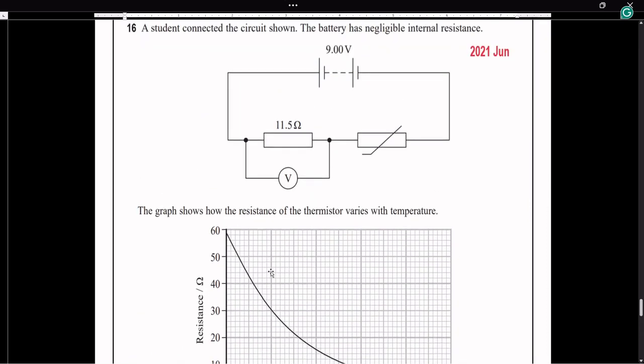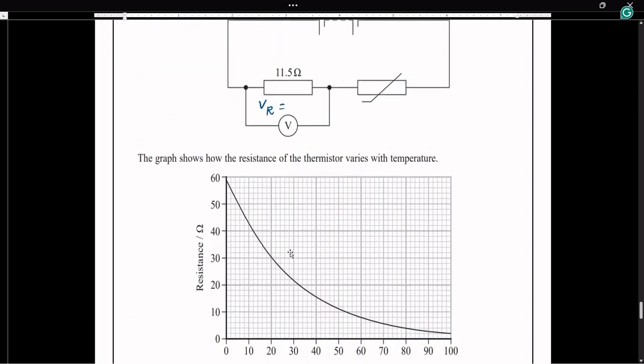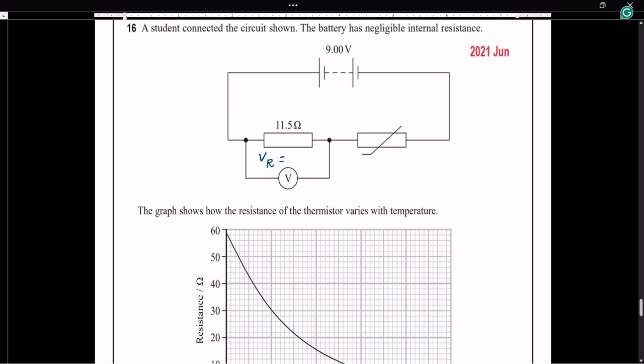So reading on the voltmeter is 3.42. So where is the voltmeter connected? The voltmeter is connected across a resistor. So what is given here is VR, the drop across the resistor, which is 3.42 volt. Therefore, we can calculate what is the current. This is the current starting from the battery source I, but the same current is flowing through the resistor as IR. The resistor is given, the voltage is given, therefore we can calculate what is this IR.